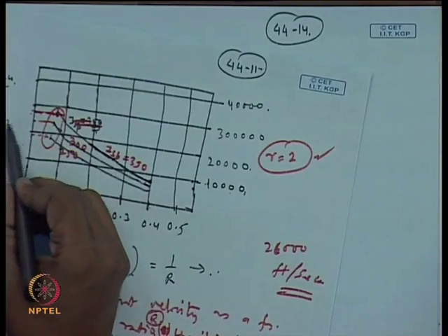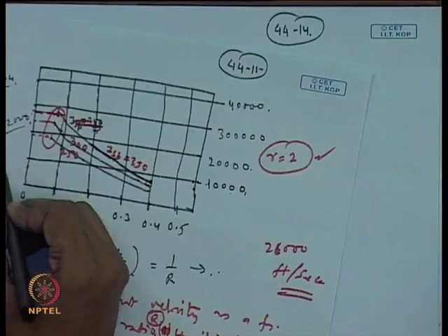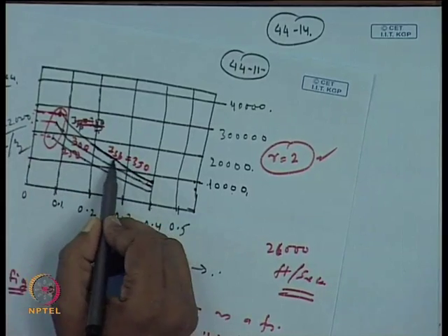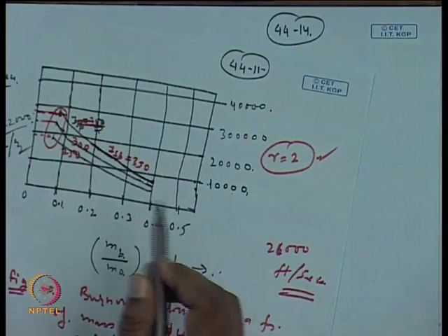While the burnout velocity which is available to us will be confined to around 22,000 feet per second. The figure is not very exact. Here, this will be around 22,000 feet per second that we get with the ISP of 350, say.